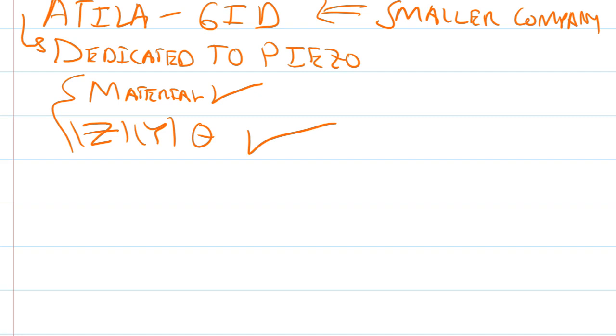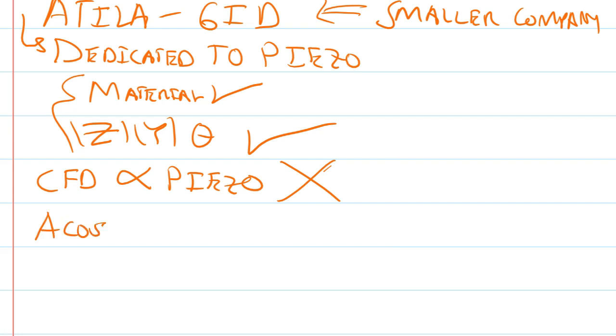So if you're going for a CFD coupled with piezo, which would be an enormous simulation anyway in Ansys or Comsol, then you can never do that here. But acoustics, either in water or in air or another medium, and piezo, that is something that is commonly utilized in this program.